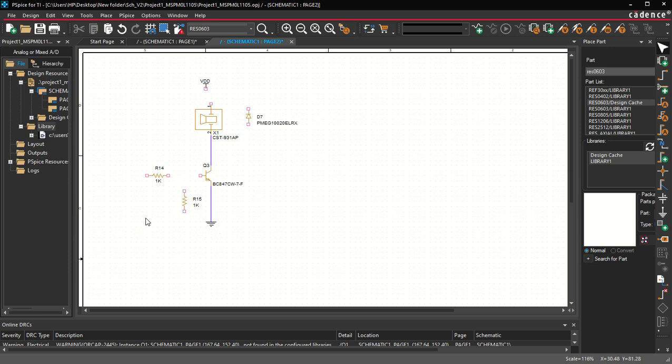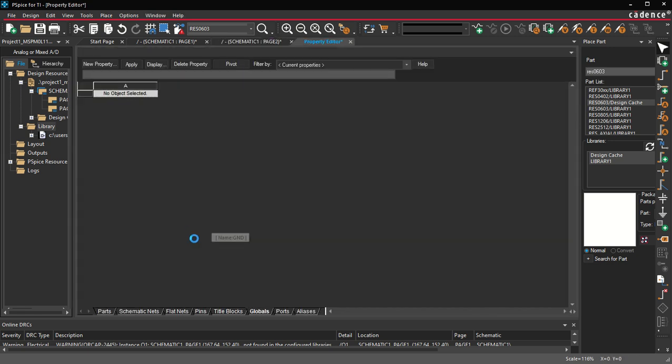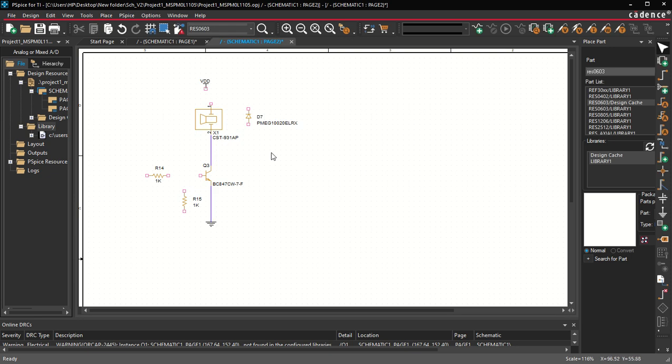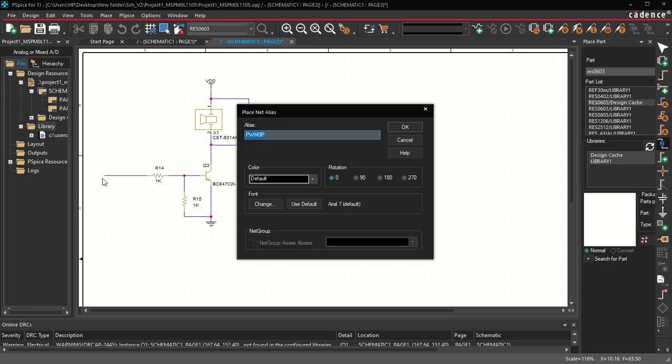So we are going to connect my ground to this as well. Let us connect this way, then this is going to get connected here, and this will be my voltage division for supplying to the base, and this is the place where we have to give the PWM, right?